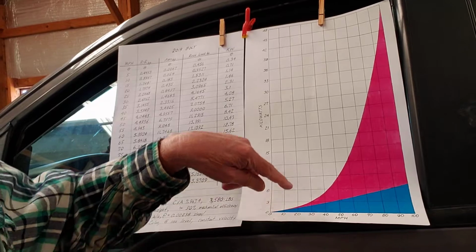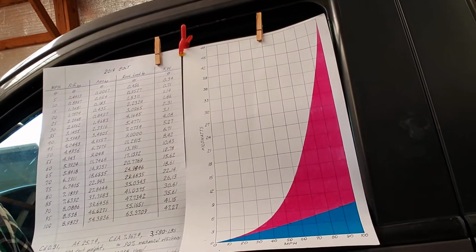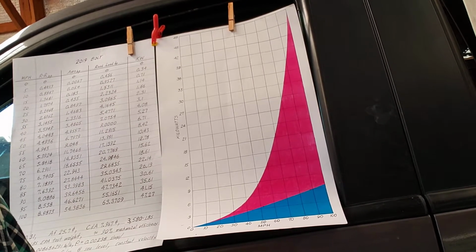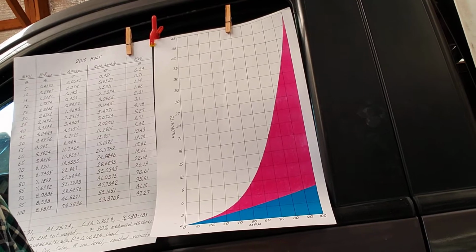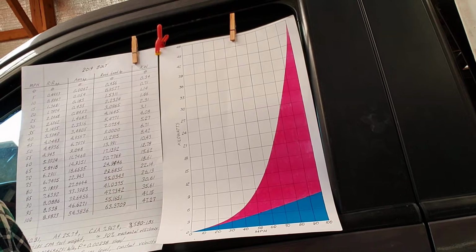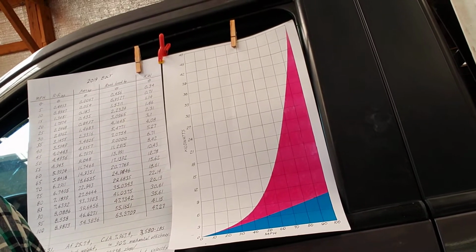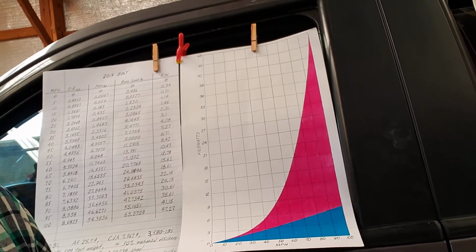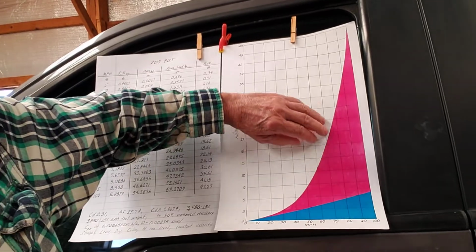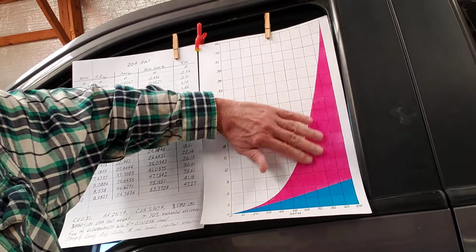But as you can see, aerodynamic drag is not. It's a cubic function, and it goes up rapidly the faster you go, especially for a higher drag shape. The Bolt, as I said, has a drag coefficient of 0.308. And let's say a new Tesla is 0.23. So this is part of the reason Tesla's performance at highway speeds is much better than most other legacy car makers, because they're not paying this penalty right here.